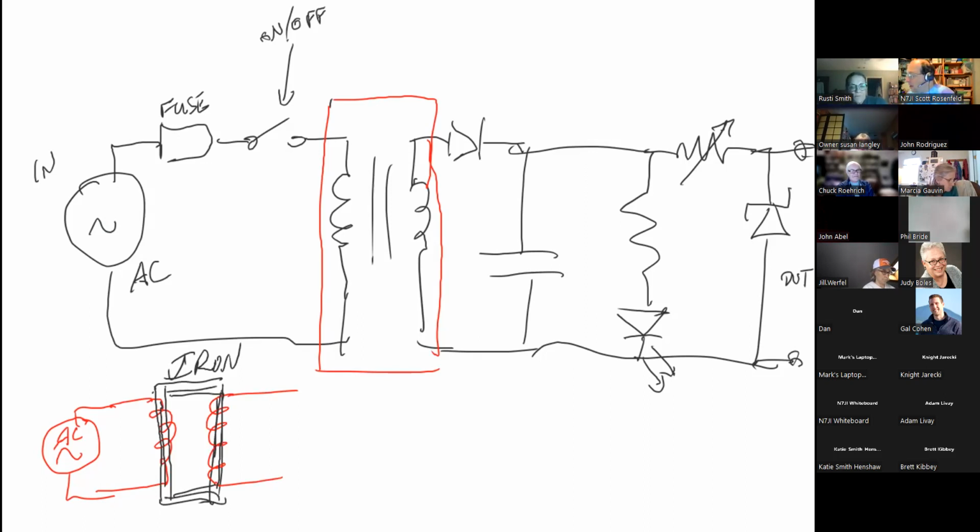air. And now we've taken another coil of wire and wrapped it around the other side of the core. So what we've done is basically contained our magnetic field inside the core, and then run that magnetic field on purpose through another set of windings. And that, depending on the number of turns of wire in that particular coil, N1 and N2, that determines the voltages.